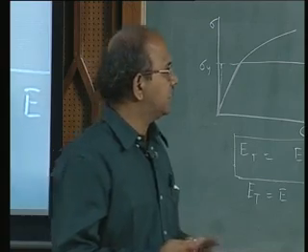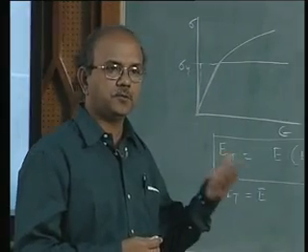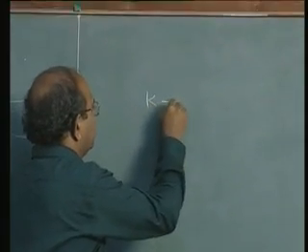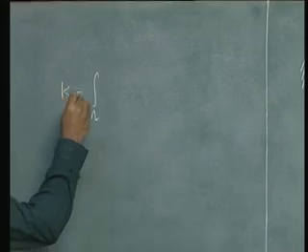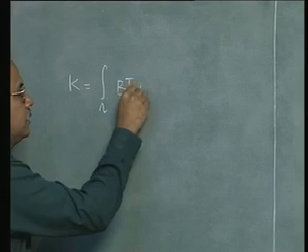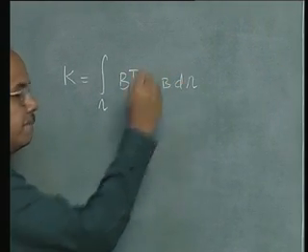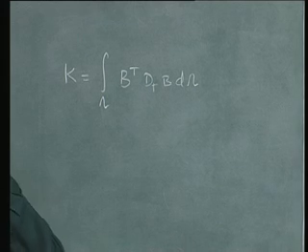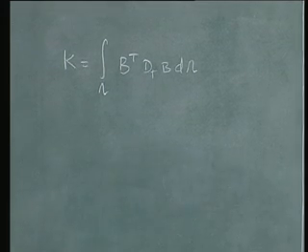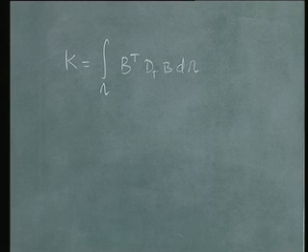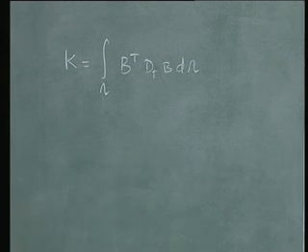Okay. So, we said that we should start with that B transpose sigma. We had already seen that this whole stiffness matrix K can be written as the integral of B transpose Dt B d omega. So, what would happen for a one dimensional case? Even looking at it, you can say that there is no big problem. Looking at it, you can say that the tangent stiffness matrix